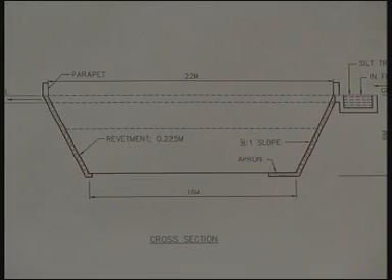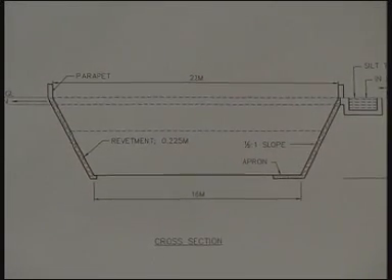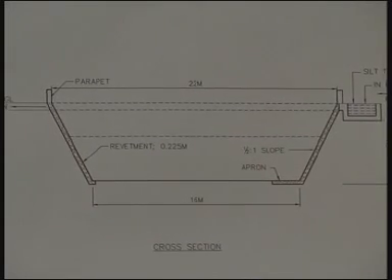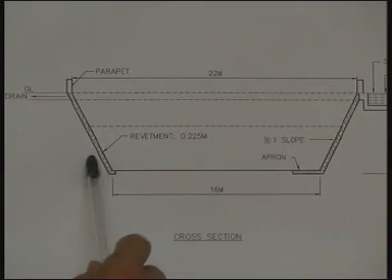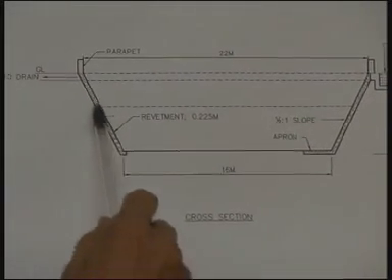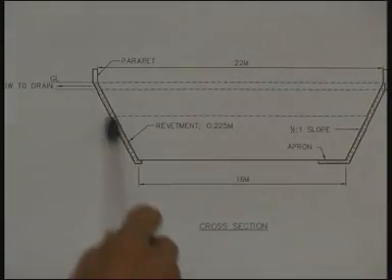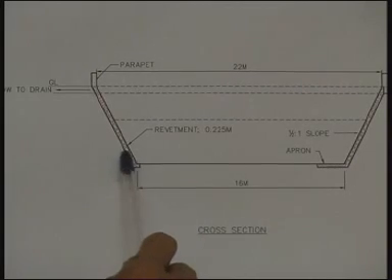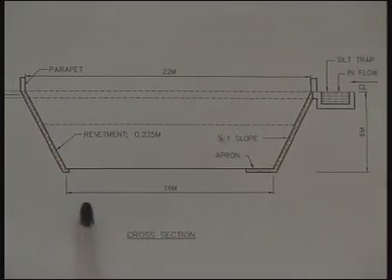Even in the house premises, the rough stone used is just dry and without cement. So therefore, it is possible that water can seep through without any hindrance. The purpose of this revetment is to retain the sides, otherwise the sides may collapse and it will silt up here, reducing the capacity of the pit.